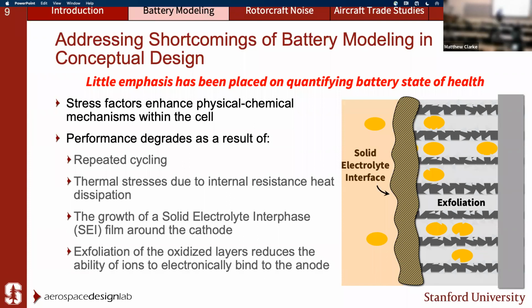Well, when you're discharging, you're essentially moving these ions to the other side of the battery. Over-discharging means that you're ripping the last set of ions on the layers over to the other side, but this causes exfoliation, right? Exfoliation increases the sizes of the van der Waals gaps. And as these van der Waals gaps increase in size, you decrease the potential to hold more charge. And that is what it means by a battery losing charge, right? I think that really summarizes what it means.